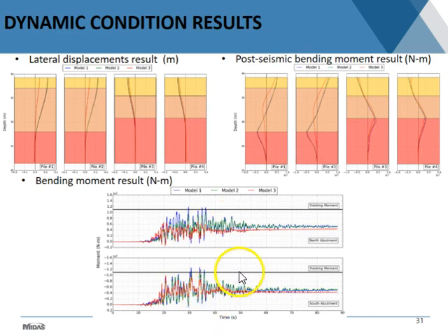Depending on the model that you look at, you see that the moments get larger and larger, and during shaking there are some points that, based on this model, go above that resistance. The residual ones are really far from the resistance, but during the earthquake you may reach some large bending moments.